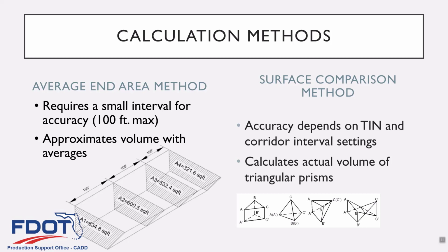And if you want to make it more accurate, basically just decrease the interval on areas where there's more complexity. Areas like radius returns, intersections, curb ramps, median noses, anything where there's tight radii happening. That's where you want intervals to be tighter, and it may be an interval, or it might be a stroking definition if it's a linear template, or if it's just a surface template and lines that you built off of.